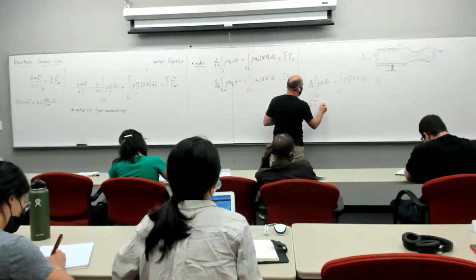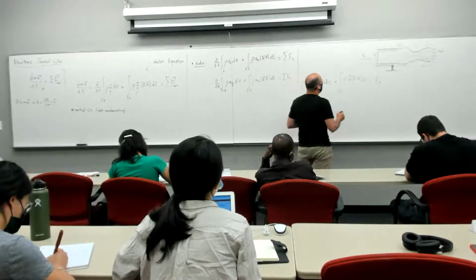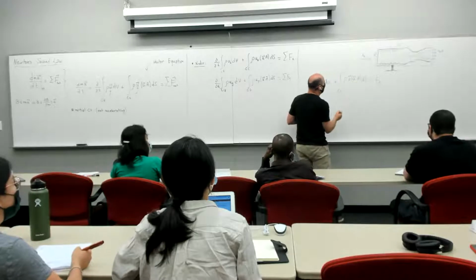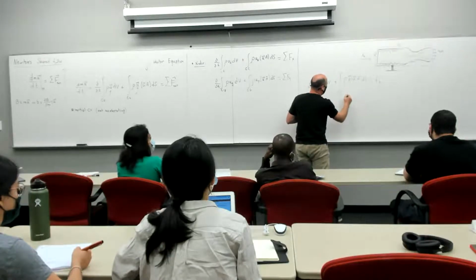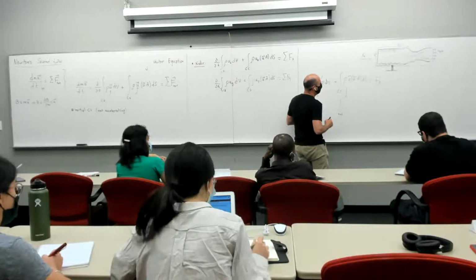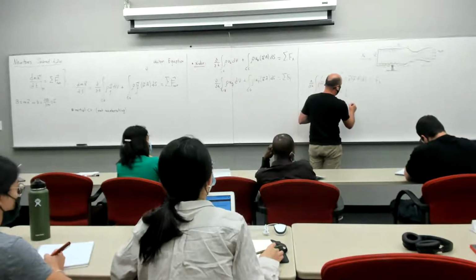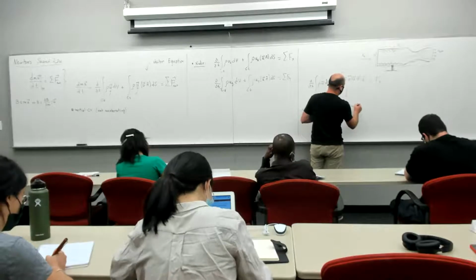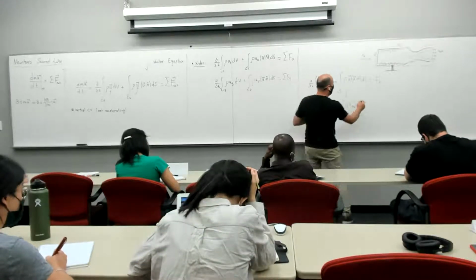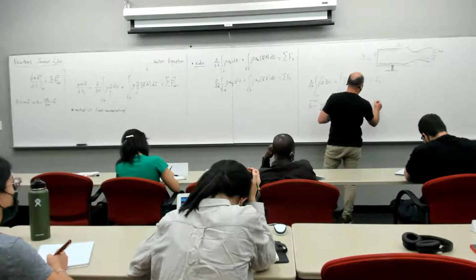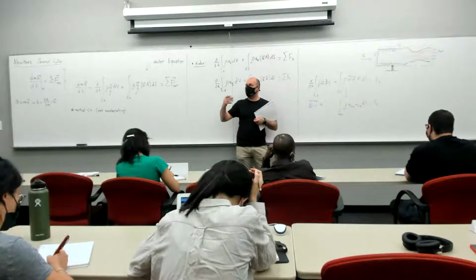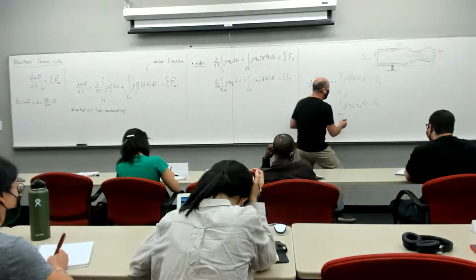Now for this term, the only control surface that matters is the outlet surface, right? So over the outlet surface, you have rho u out times u out times dS equal to Fe. Now u out is constant, and density we also assume is constant.